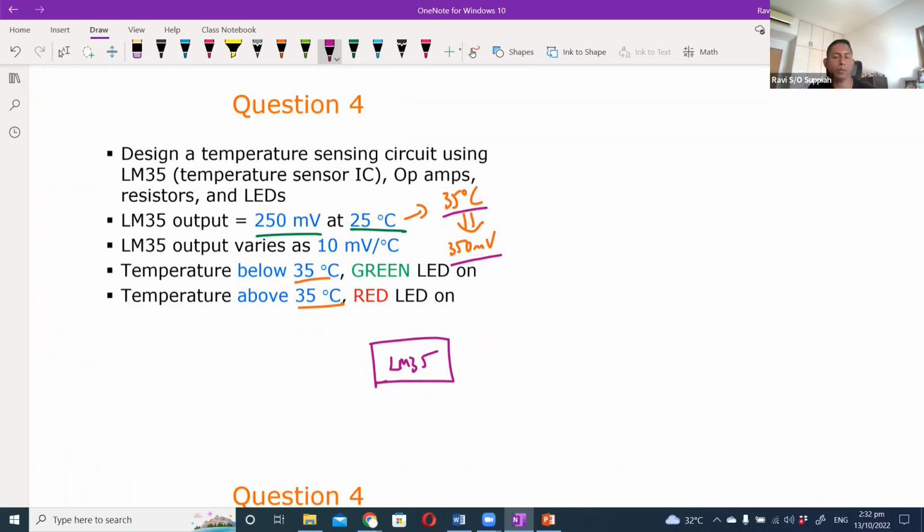If you use your scope and make the voltage scale resolution as small as possible, you'll notice it's never a clean line. There will always be noise, which means it's very easy to get false triggers.